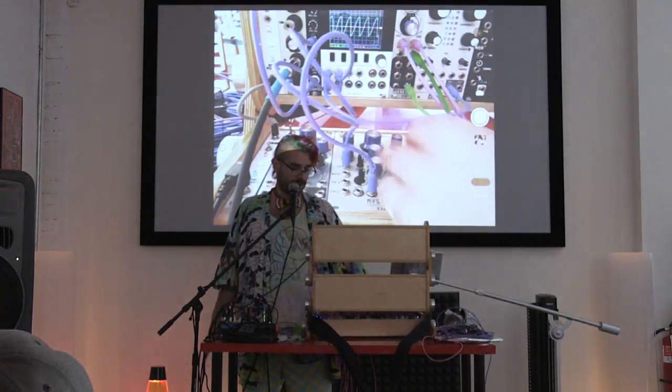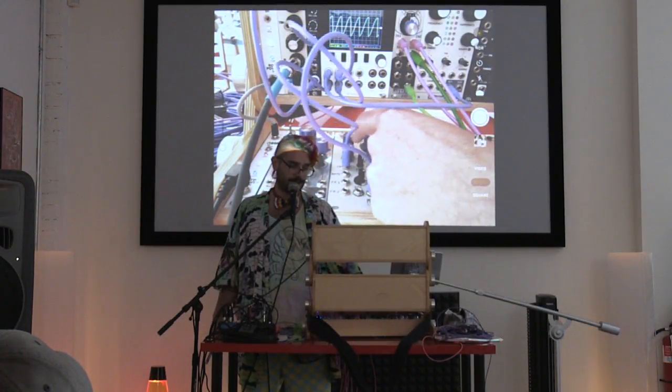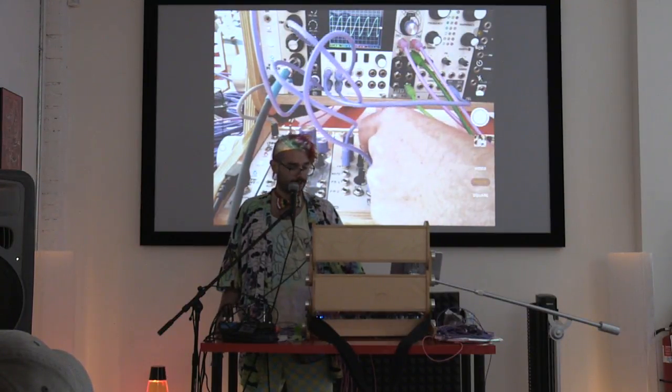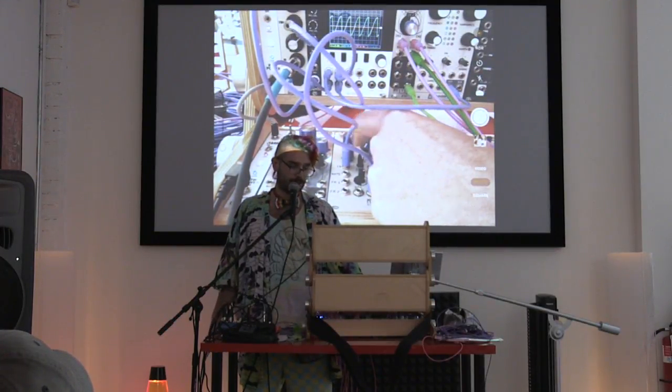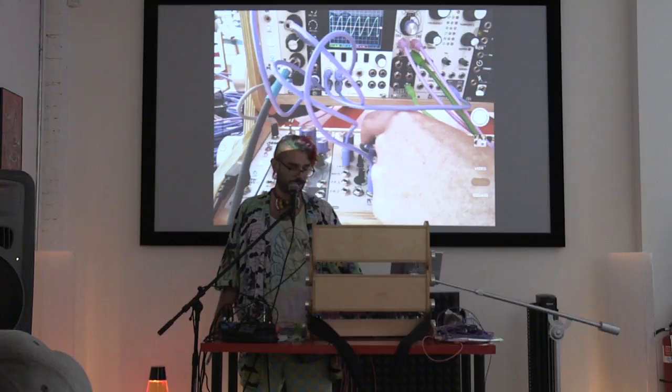So with most downsamplers, what you're getting is basically only sampling, and you're able to change the frequency of the sampling, which basically lets you turn your input into a bunch of little stair steps. The nice thing about the Spectra Mirror is that it lets you decide how much of that effect you're getting by controlling the pulse width of the internal oscillator. It also makes it so you get these cool kind of like tremolo effects at slower frequencies.